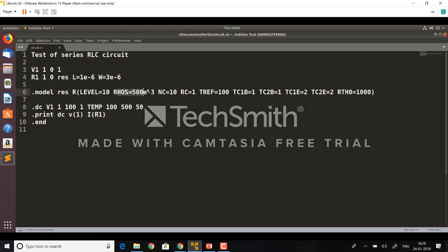You define a sheet resistance. Since these parameters don't exist in the Verilog-A code, the simulator will simply ignore them. You can leave them here. You don't need to care about those. We'll be using these parameters for higher models. Just keep it there. We'll use the same netlist. Then what we're trying to do is sweep. Let me do a simpler one.